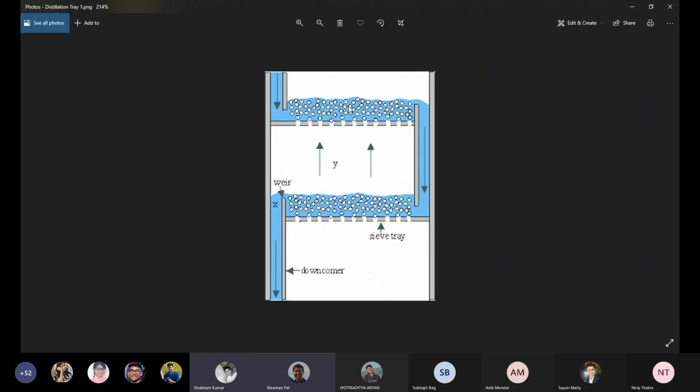Top section, it's the wrong answer. Say bottom section. If it is the top section, how is the vapor moving up then? The bottom section has the highest pressure, and the top section, especially the pressure of the condenser, is the lowest. The pressure in the reboiler is the highest.